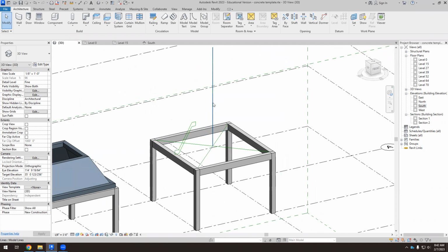but this is the first thing. We need to create this axis, and then we have to rotate this shape about this axis. So sweep is create a path, and then move this shape along the path. Here I have to rotate this about the axis. So it's a different way to look at things. But now I think it will work.